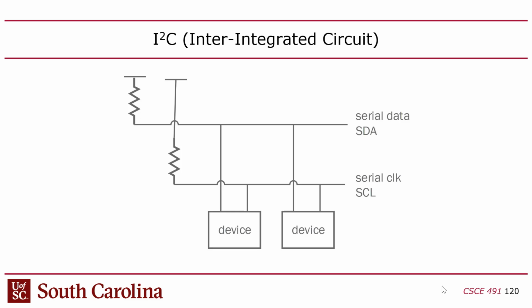But like I mentioned to you in class, nobody ever uses the bidirectional nature of SPI. It's never taken advantage of, because generally speaking, when you do an SPI transaction, only MISO or MOSI is being used and the other one's just idle, right? So it makes more sense to just have a unidirectional data wire. Make sense?